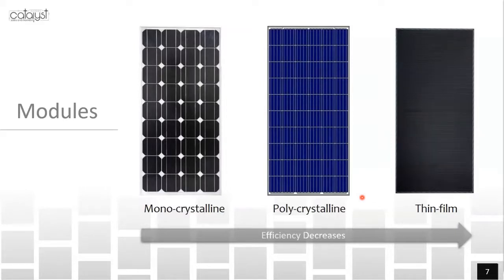Right now, not what a manufacturer may publish on their website or tell you is conceivable or what's coming down the pipeline, but what you could actually buy today in a 60 cell, you're ranging from 250 to 325 watts, and a 72 cell is ranging from 300 to 400 watts. So that's the modules. Pretty simple, pretty straightforward. Not a lot to differentiate there other than price.